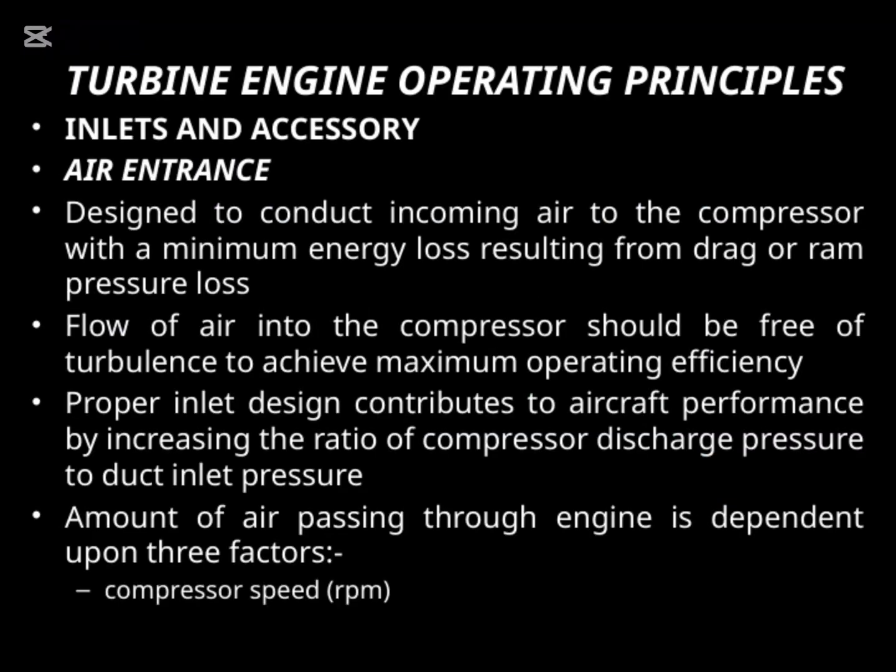Let's get started. Let's take a closer look at the turbine engine operating principles, starting with the inlets and accessory air entrance. The main goal here is to efficiently conduct incoming air into the compressor while minimizing any energy loss. This means designing the inlet to reduce drag and avoid ram pressure loss, which can negatively impact performance. It's also crucial that the airflow into the compressor remains as smooth as possible, without turbulence. Turbulent air can reduce efficiency and cause uneven compression.